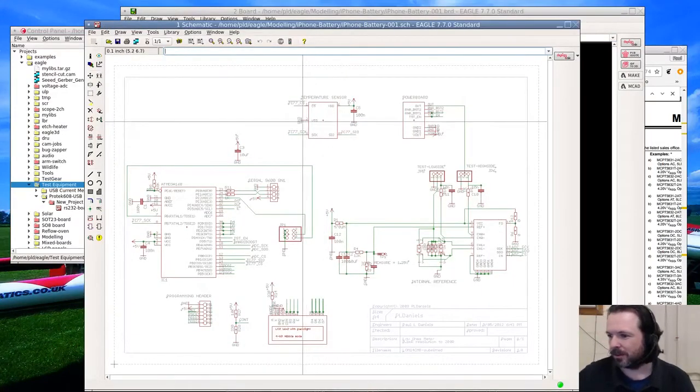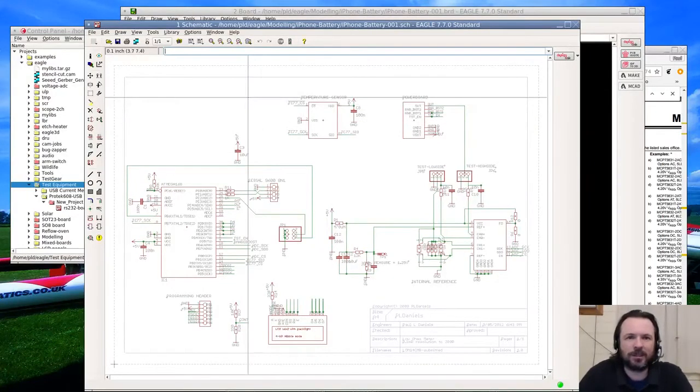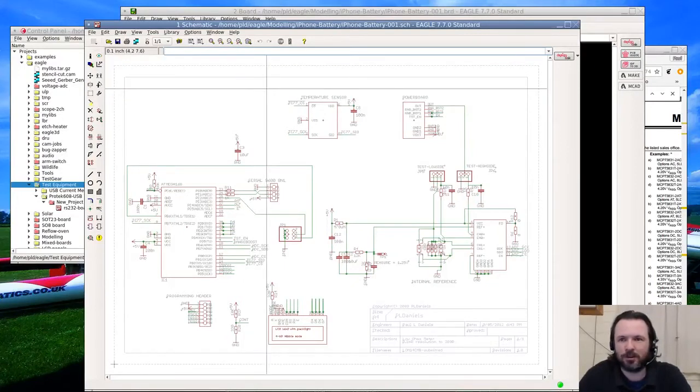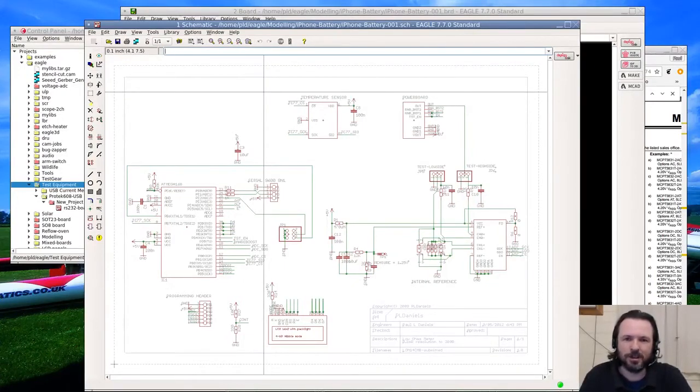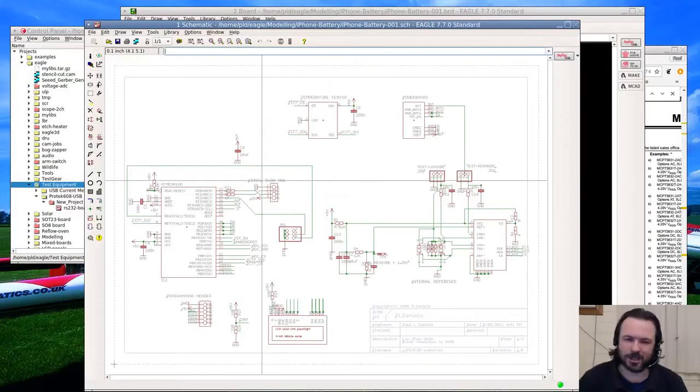Can you use a trim pot in place of R1 to make it easier to adjust? You could, but cost was the primary driver of that particular project. So it's easier just to stuff around with one board, get the resistors to the values you want, and then just do it 100 times over. Particularly when the resistors are 1/10 of a cent each, whereas a trimmer is a much bigger device and you're looking at at least 20 cents. Okay, maybe 10 cents, but that's still 100 times more expensive than the resistor.